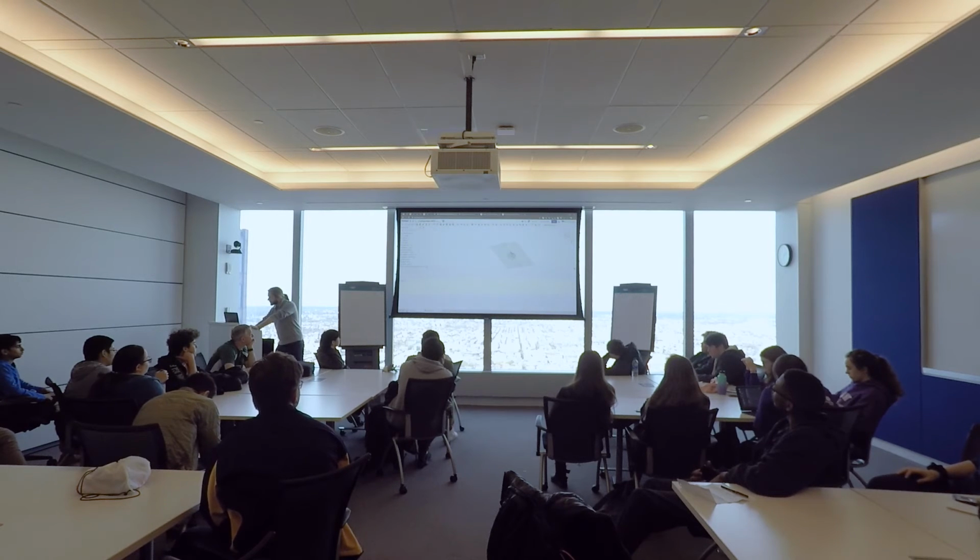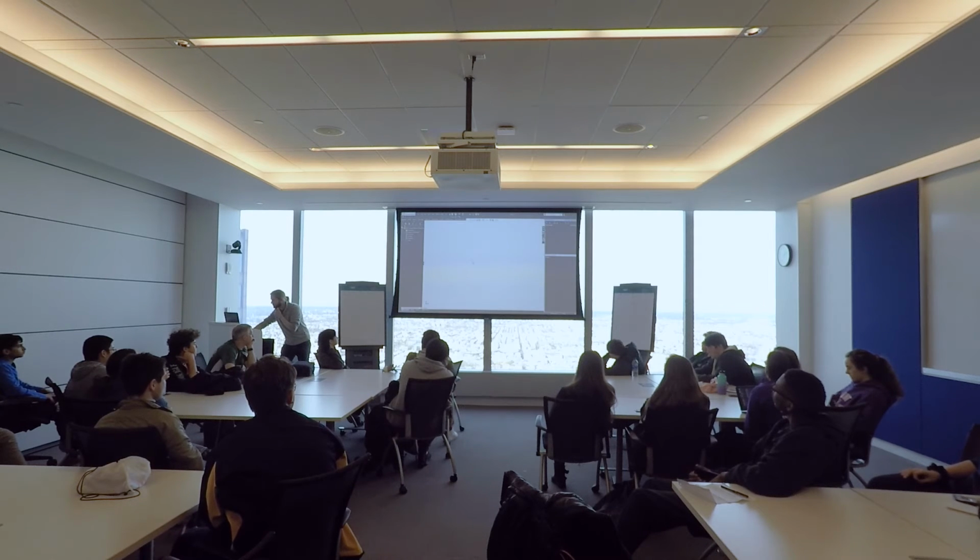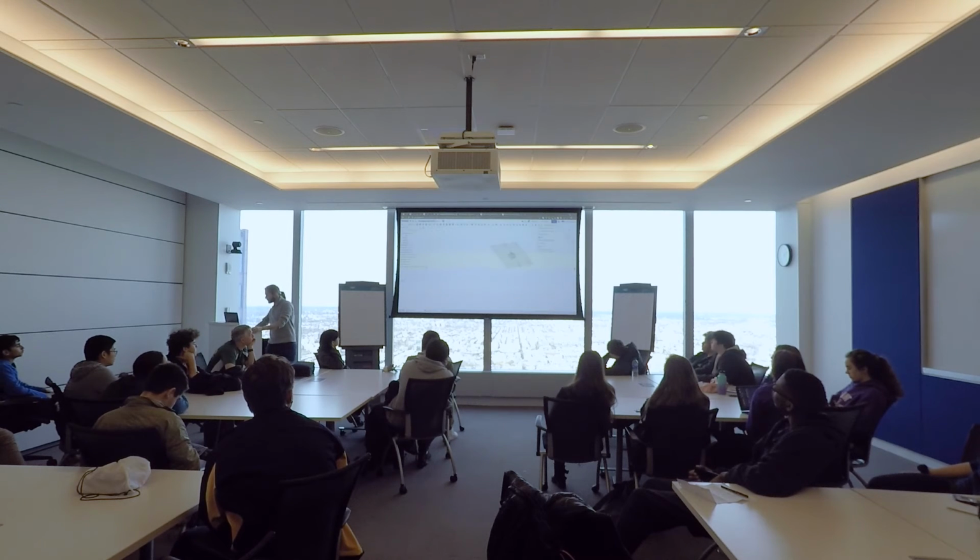Now I can use this sketch with something called the beam tool, which is over here in Onshape, and it's called structural elements in SolidWorks, I think. Let me pull SolidWorks up. Weldments, it's called weldments, that's what it is. Structural members, weldments, it's the same thing. So I'm going to do beam.